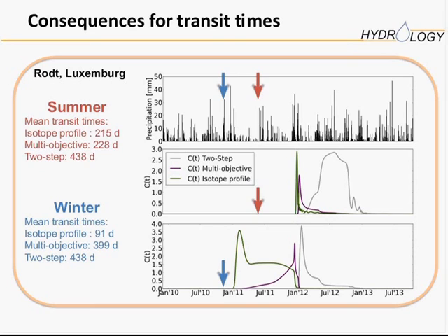However, if in your climate region the water vapor concentration is relatively high, you may have 85-90% humidity, and then you have a small temperature change. There you certainly have that problem. But then if you dilute that from 90% to 50% relative saturation, you are still around, depending on the temperature, 10-15,000 parts per million, which is still a very good range for your analyzer, if you do the calibration also for that range, or you do a good correction for your water vapor in your analyzer.